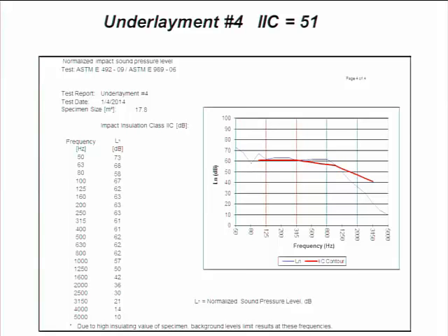We evaluate the performance, at least in the lab we do, of a test assembly by examining different individual frequencies. An example is some of our clients may expect higher IIC results for perceived product improvements, but they do not see an increase in the IIC. But we may see substantial improvement at different frequencies when we're doing the test, but it might be limited by one particular frequency. That one slide with the 8 dB limited that particular assembly to a 49 instead of a 50.